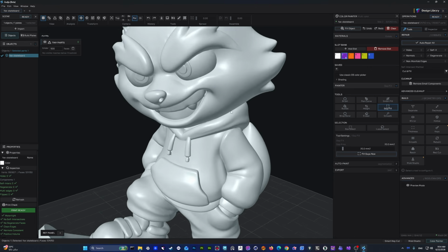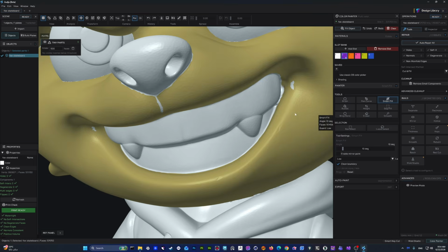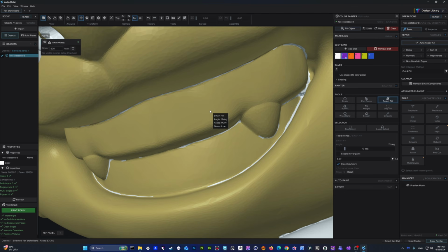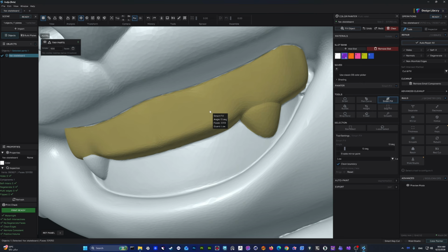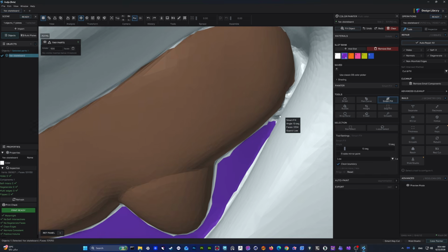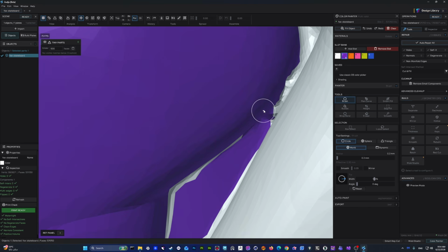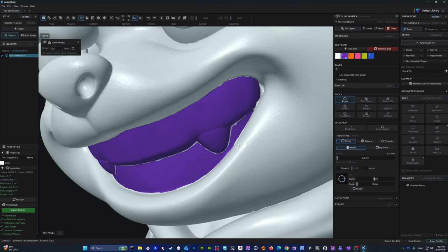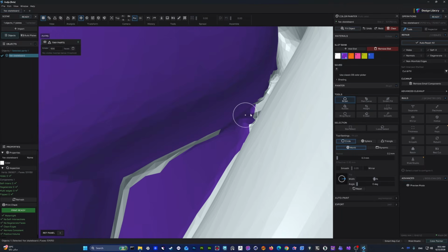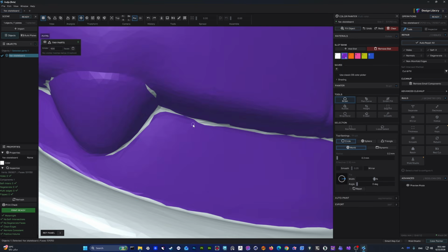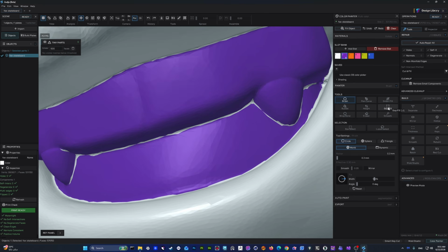And we have here the gap fill, and that's so important. So let's say I'm gonna use smart fill for this, and I'm gonna just press shift and right click. That's base detection. If I increase it more, as you can see, it detects more parts I don't want. So let's say I'm gonna decrease it a little bit by moving my mouse to the left or right, and the same down. And I'm gonna close the open edges of the model. As you can see, I close it from here, and I'm gonna close it from here. So the whole part is actually painted the same color, and there is no leaking of the white color within the whole mesh. So as you can see, this part is surrounded with the purple color, and the white inside is too much actually. But we can do a gap fill.